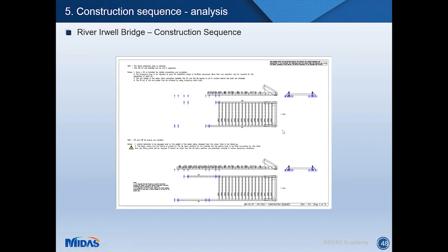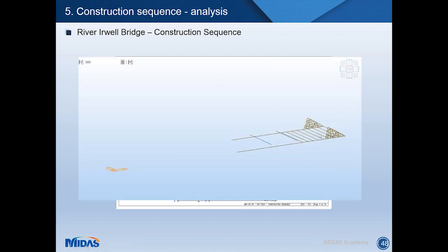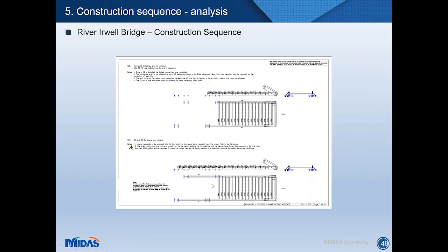So how do I model this directly into MIDAS? So what I want to represent is this first stage 3, and then this at the end of all I did. Please notice that when the central tie beam is erected over its temporary supports, there is no connection between the central part and the northern part, and this needs to be reflected in our modeling.